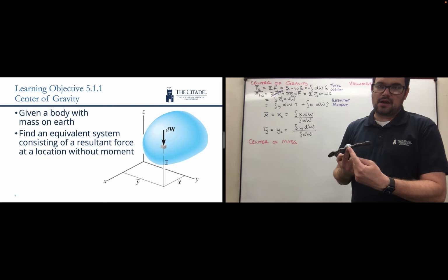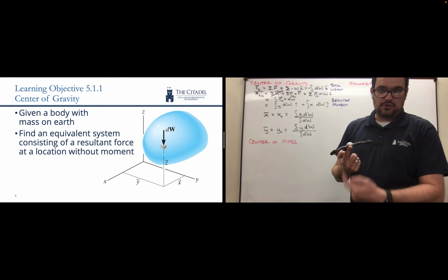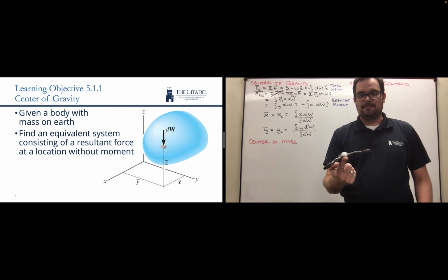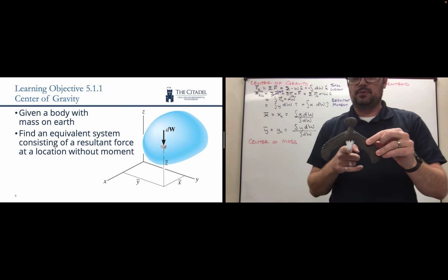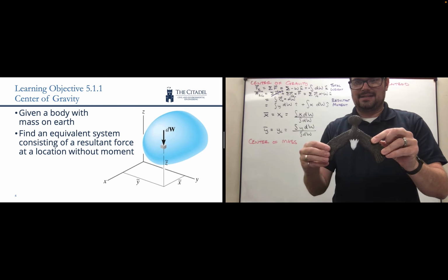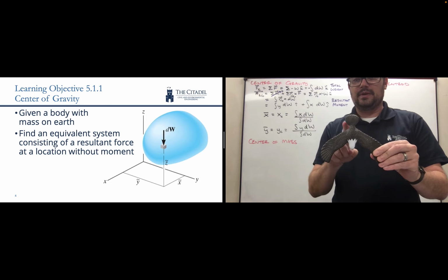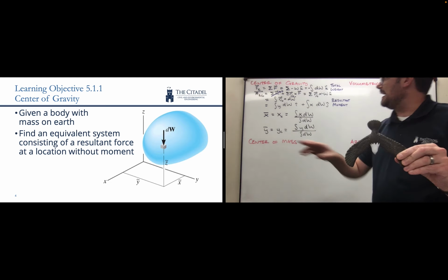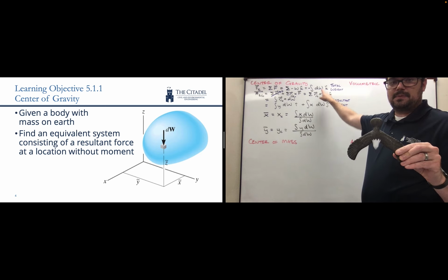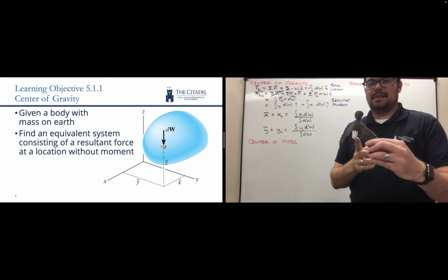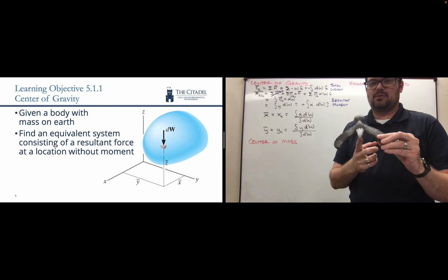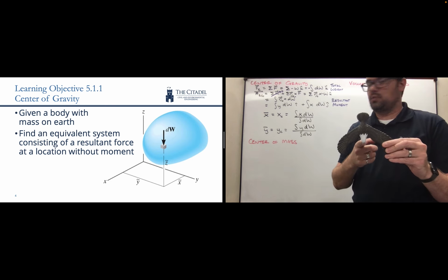So it turns out that our resultant force location, or the center of gravity, is in line with the beak and slightly below the beak so that it stays stable on my finger. And what this is doing is evaluating in terms of a plan view. If we think about the overall mass, we can calculate the overall total weight by integrating with respect to the weight, and then we can think through the moment that would generate motion about the x and the y axes, z coming out of the board towards you.